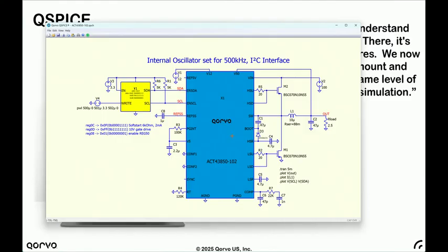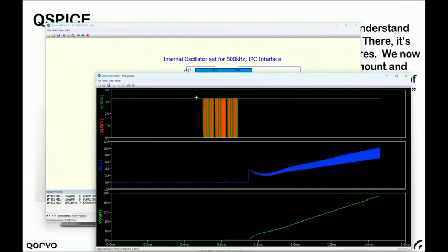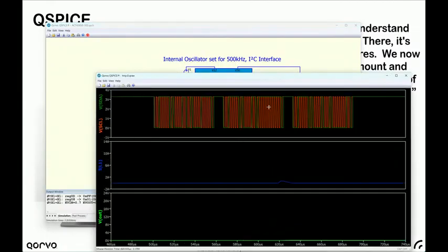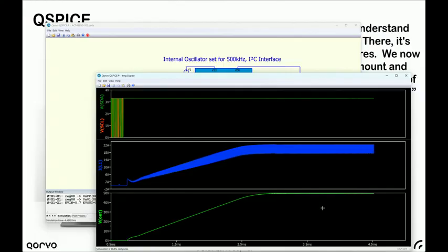It's the soft start. It's how the soft start behavior switches over to a low pass filter if you use it as a reference voltage instead. It's the commutation dead time. It's the gate voltage. Here I'm using JFET, so I have to be careful with gate voltage. Anyway, when I run this simulation, that's the I2C clocking in data. It has no impact on the simulation speed of the rest of the controller. So that's a half-bridge simulated thing.